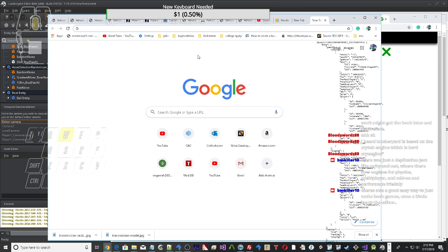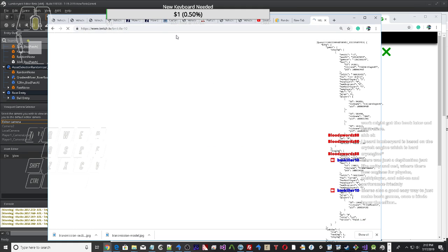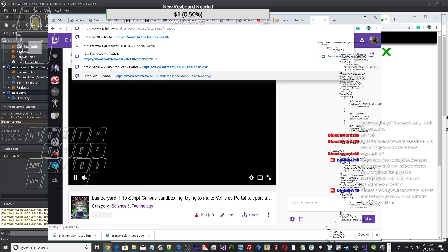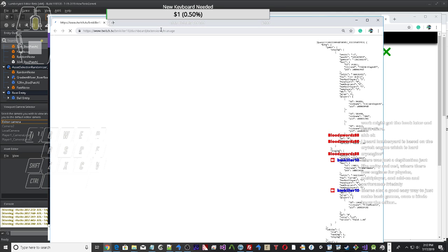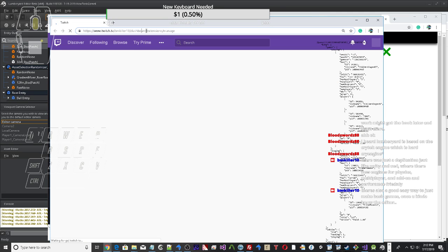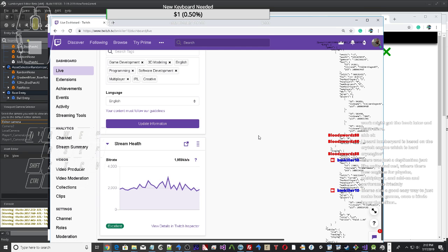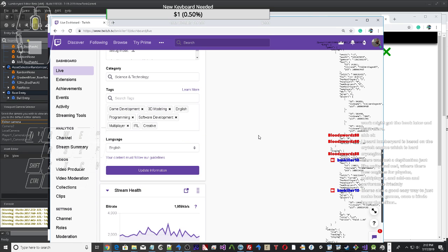So, if we know v, and the constant ρ, then we can define the longitudinal slip as the ratio ωρ/v - 1, so that it's 0 under free-rolling conditions. Just looking at this formula, a free-rolling wheel has κ equals 0, a locked-up wheel under braking has κ equals -1, and an accelerating wheel has a positive κ of any value.